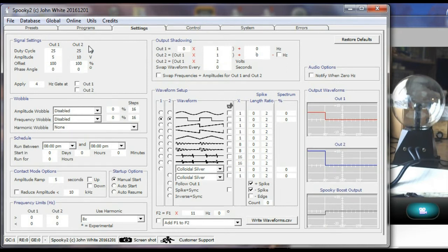And I'm choosing that only for this video so you can see the blinking of the plasma ball. So what I'm going to do is put a minus sign, 29,999.5, and that will create a 1/2 hertz. If you subtract that number from 30,000, you'll get 0.5. Isn't that amazing? It's a minus 29,999.5. All right, let's test the program. Go to Control. Well, let's make sure that latched in. Go to Control.